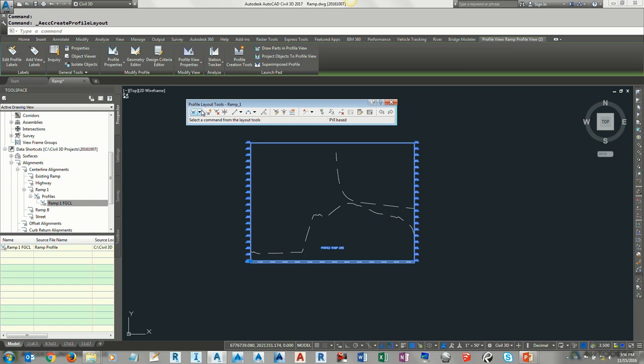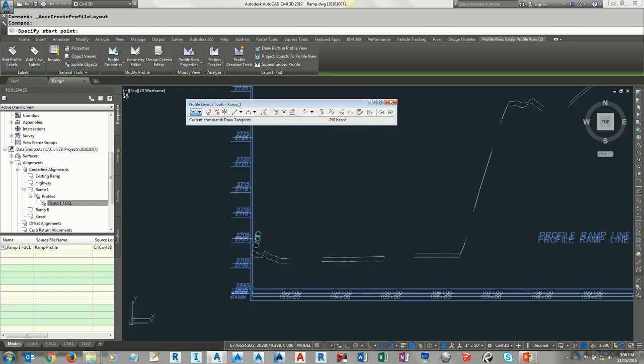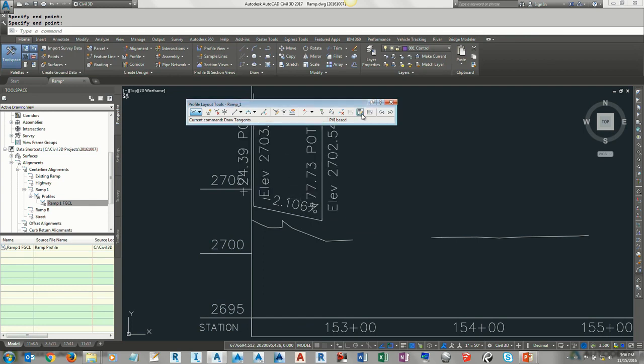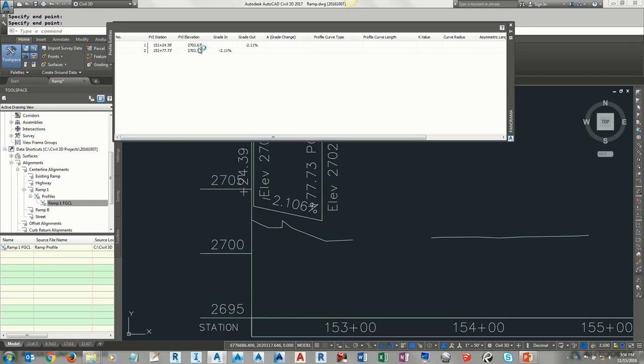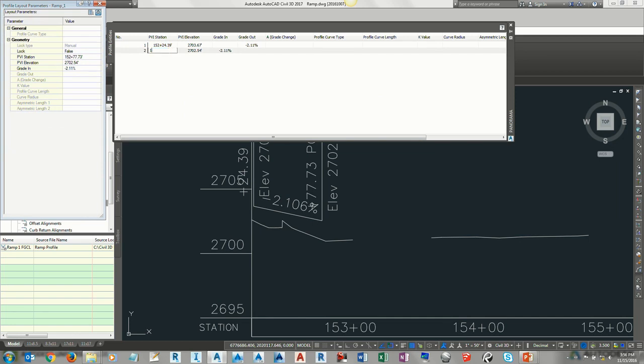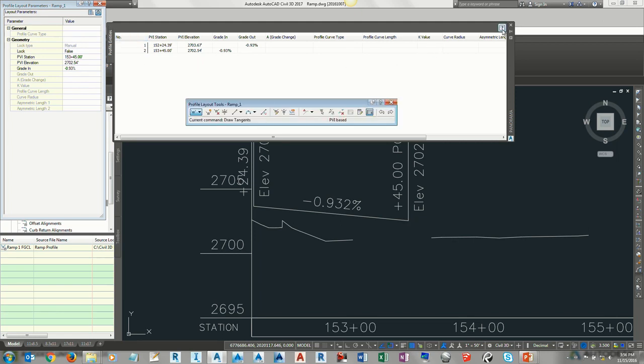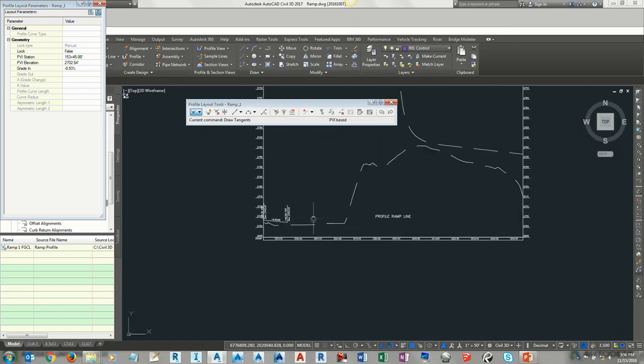And so I know the first two points, but basically I can kind of draft something. There is a center line here somewhere, and there is a specific grade that goes on to, so I'll just kind of put 2 points in there, and I'll modify them later. Start somewhere. Okay, that's fine. We can go with this. 1, 5, 3, 4, 5. Okay, so I got this very first tangent taken care of.